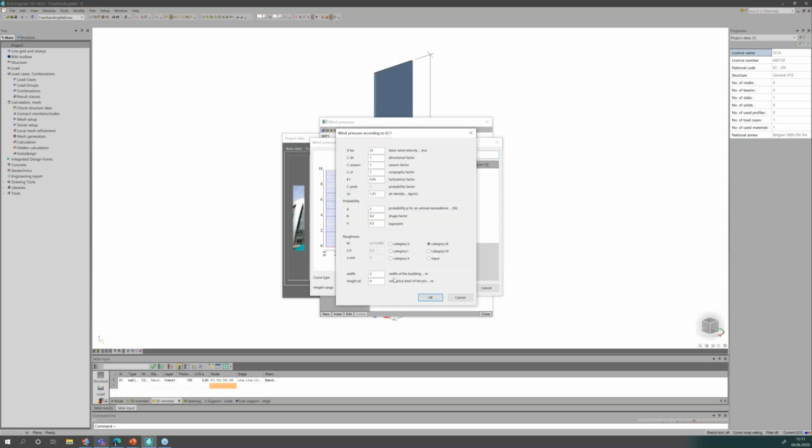What's important, and what was also visible on the dialog for the wind settings, is the item which is related to the width of the structure. The default value on the dialog is 100 meters. But we have 2 meters, and as you have seen from the presentation, it's an important value once you are determining in which of the 3 items your building or freestanding wall is.